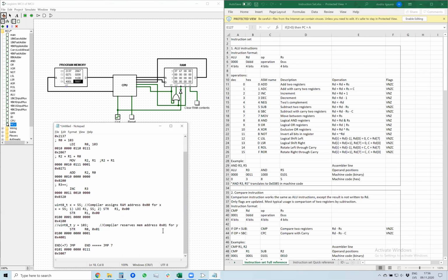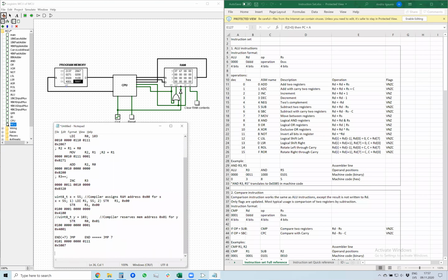But in CPUs, you can also store this number into a register, and you can do this so-called indirect memory load, where you have an instruction. Our simple processor doesn't have it, but basically all processors have it. It would be called something like LD, load into a register, for example R1, the value stored in a pointer register, for example register R5.